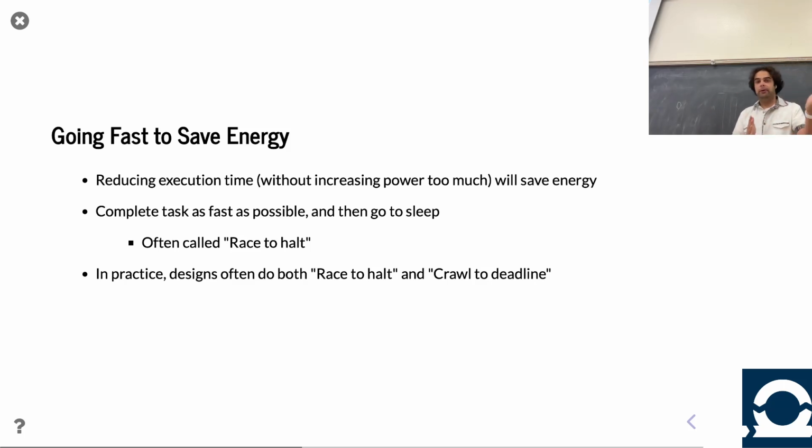Like I said, you have these periodic operations very commonly in smartphones. Things like transmitting on a cell radio, where you have a certain time slot coming up every so many microseconds. You have things like displaying video frames. You'll be amazed how even on a smartphone, when you think, "Oh, the screen is on, I'm reading a web page," it's going to sleep. Even at the human scale, things are happening. Even if you're scrolling your finger and the screen's moving, it's scrolling at 100 hertz. 100 hertz, 10 milliseconds, right? That's an eternity in hardware. Things can be put to sleep in that time period. So you're always trying to figure out ways to put things to sleep.